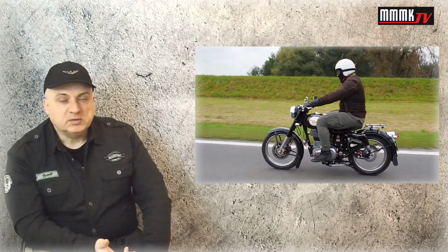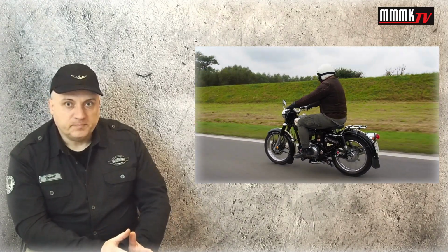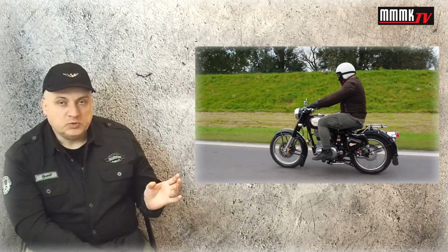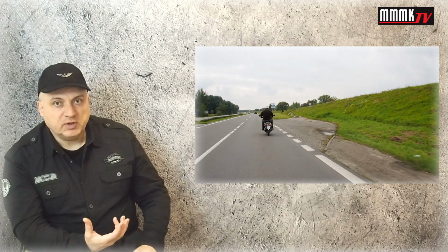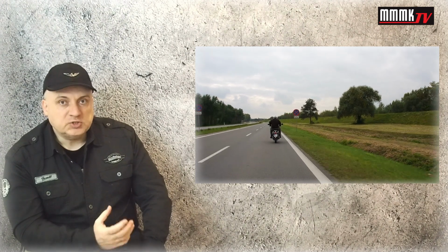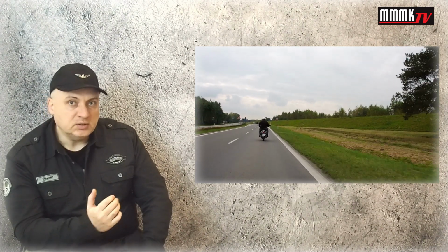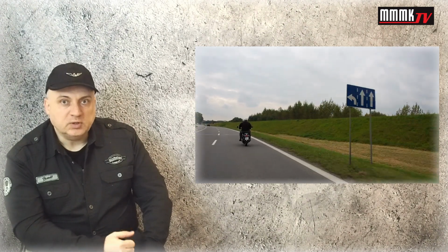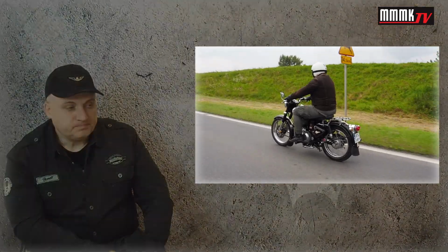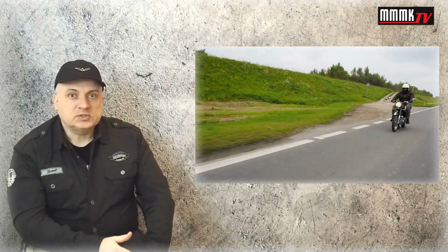Another friend of mine decided to verify it more precisely. So he installed a wide range O2 sensor in the exhaust pipe, hooked up to a reading device. And he confirmed that during acceleration the mixture goes really richer compared to the Euro 3 ECU. So we know for sure that it goes richer. If it goes richer, the next question is the fuel consumption. To be honest, we have not noticed any difference in fuel consumption compared to Euro 3.